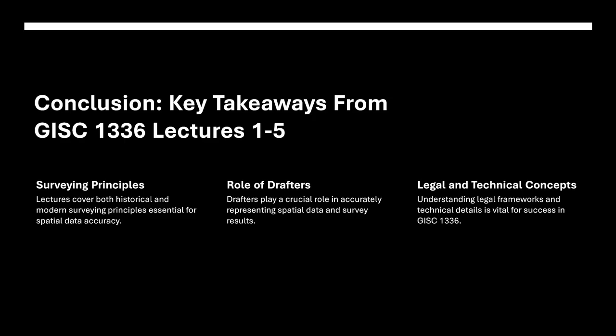And finally, in Lecture 5, we stood on the shoulders of great Texas surveyors in case law. Stafford v. King reminded us that monuments prevail and that the footsteps of the surveyor upon the ground should always be followed. State v. Post taught us that resurveys retrace, they do not redesign. Strayhorn v. Jones reminded us that rivers themselves, not meander lines, are the boundaries. Hicks v. Lovelace told us that senior deeds prevail.